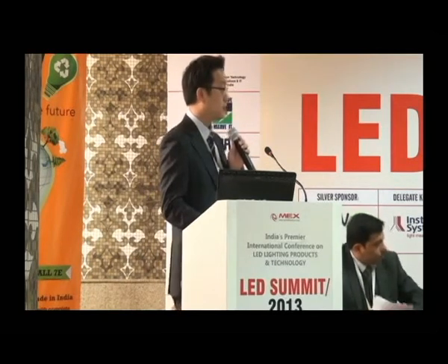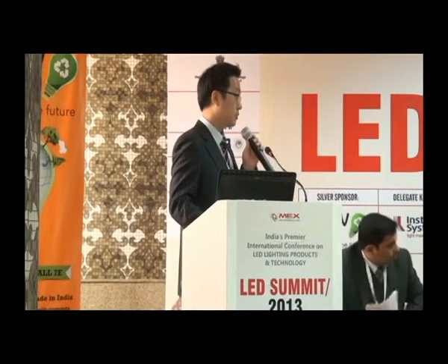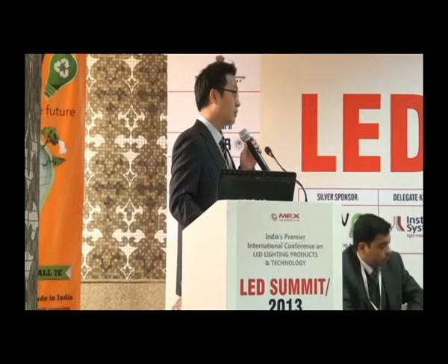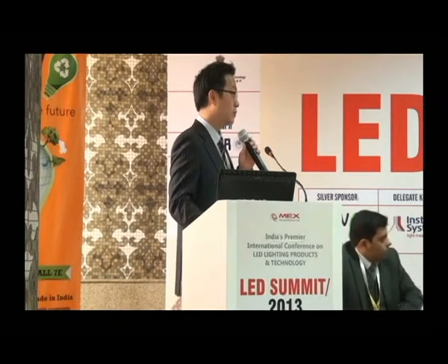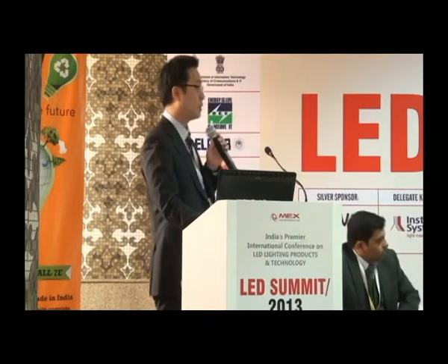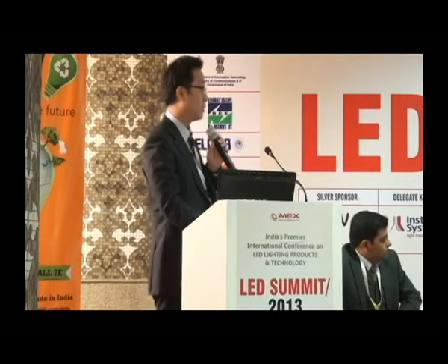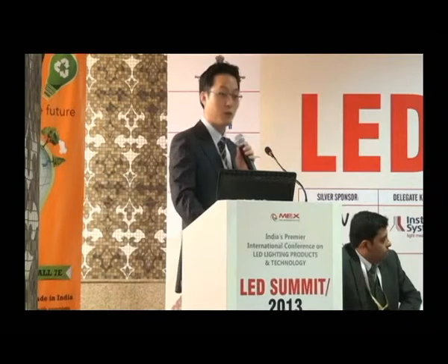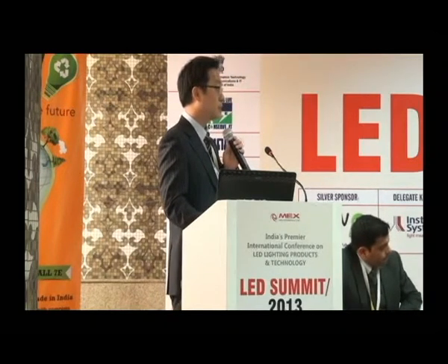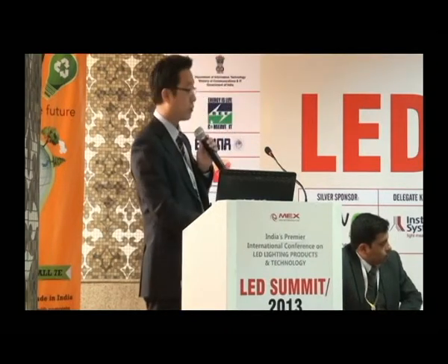This one is the LED, a conventional LED structure. There is an LED semiconductor chip inside, and then a gold wire with a frame and plastic packages. Sometimes ceramic is used for high-power LEDs. But this encapsulation part and the LED lens part have to be made with a very transparent material. So silicone is the choice for this lens and encapsulation part.